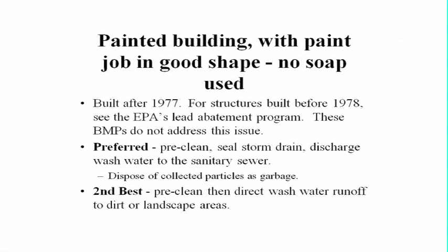There are seminars all over the United States on how to handle structures and remove lead-based paint. You need to go to one of them, and we're not going to address that. But if you test the top surface on a home and it shows negative for lead, you might need to check whether there are three or four layers of paint. If you're going to be removing any paint, you need to check the layers under the top layer to make sure there's no lead hidden under lead-free paint on the surface.